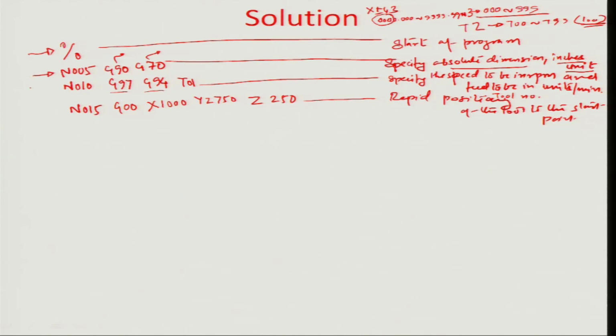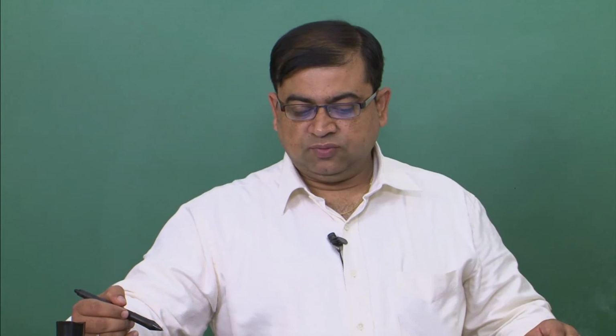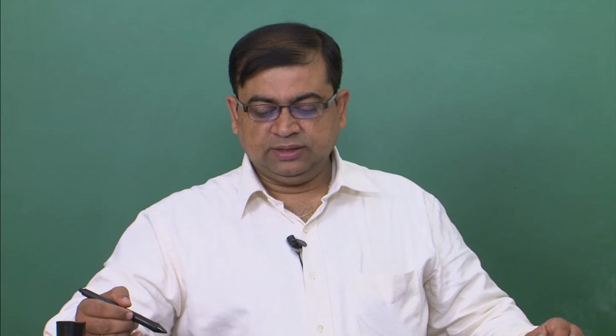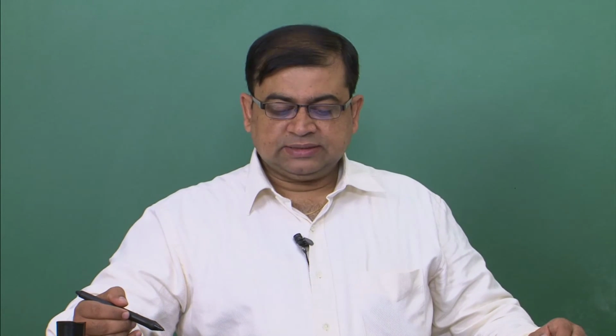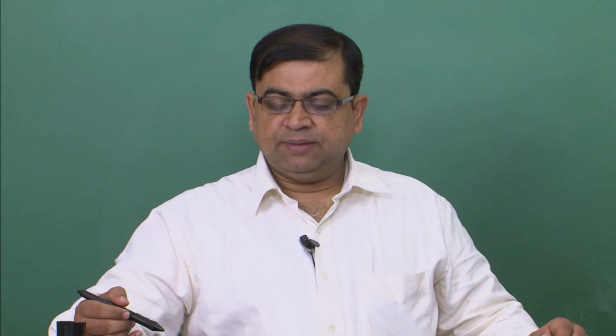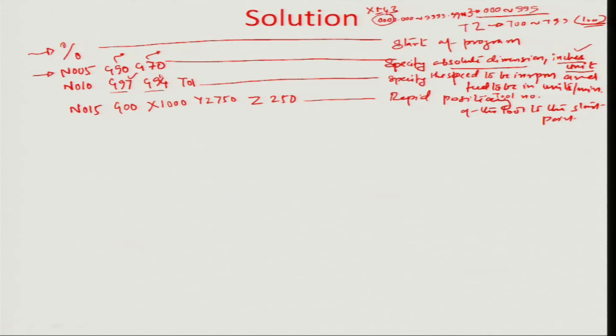We also talked about the G command needed for the system of measurements in use. It's inches, so the FPS system is used here, so inches are the units for describing length. We were also able to describe the speed in RPM and the feed in units per minute using the commands G97 and G94, and selected the tool as tool number 1.